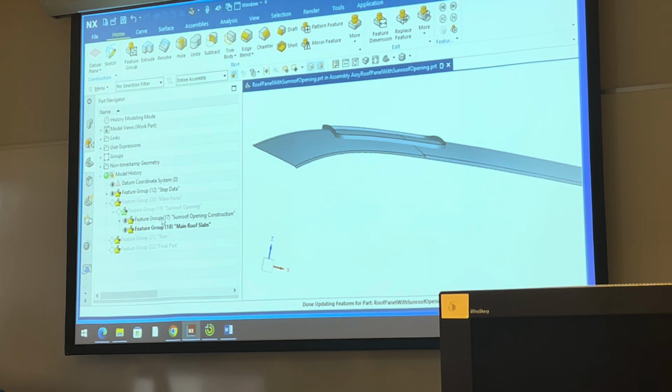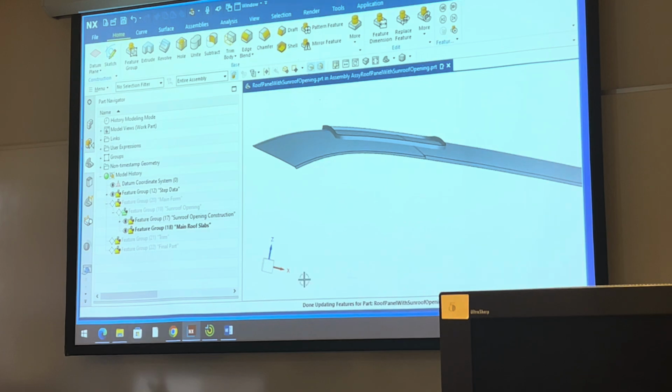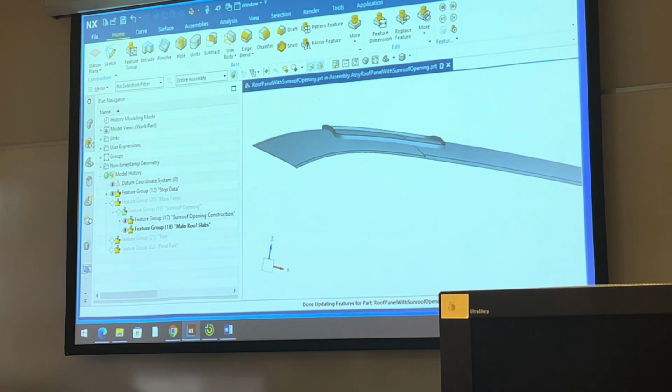You've got a whole big tree already made, but now you're thinking, oh, I forgot to add this set or this feature group. And you don't want to put it in there and have everything shift around on you. Go to where it's supposed to go and make it active, the feature group that you want it to go in. Make that active first, and that usually keeps everything else from moving around. The rest of the tree just sort of didn't get affected at all.